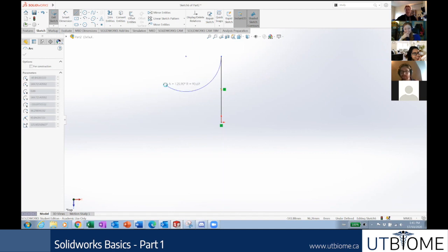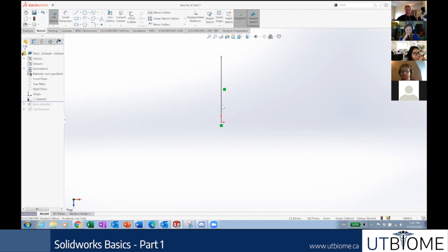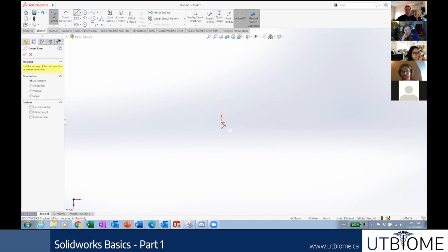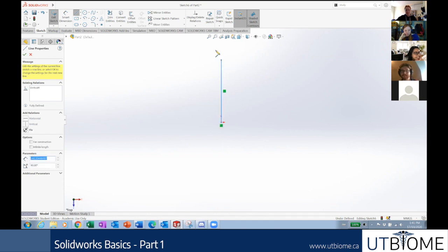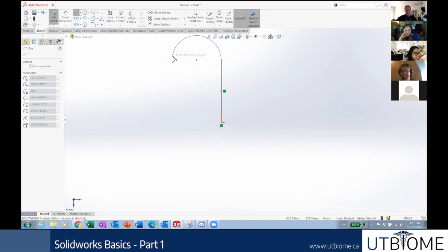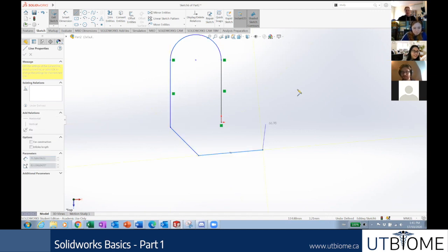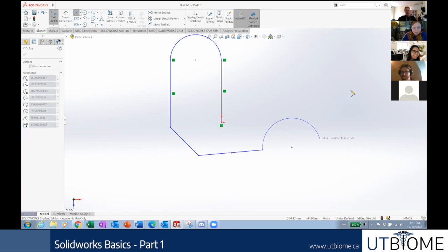So I'm just gonna hit escape here because I don't do it that way. I do it the really cool way. So we're gonna go back. I'm gonna draw a line. It's gonna go up. I'm gonna just click it. So now instead of going back, if I just press the A key for arc, it draws an arc. I know, pretty cool. And so once again, this follows the line rules before. As soon as I click, I'm back to drawing lines. I don't have to do anything special again. If I want another arc for whatever reason, I draw another arc.